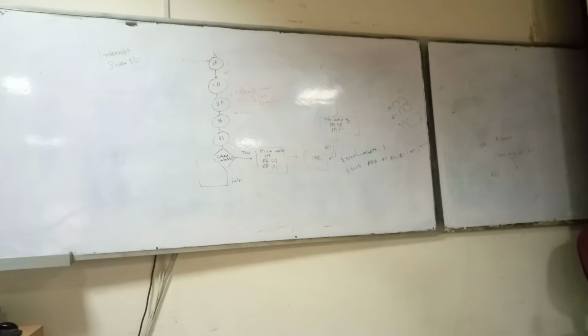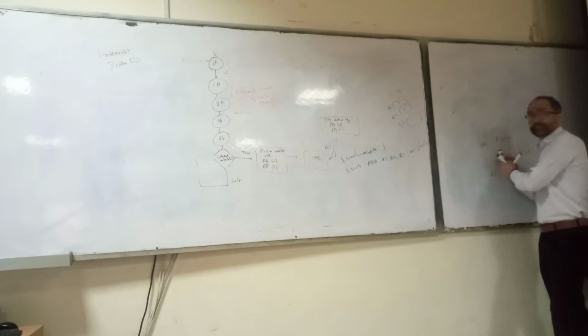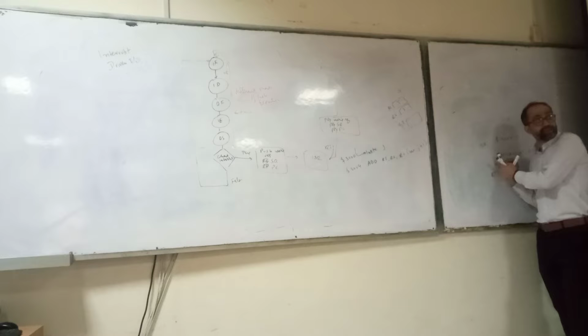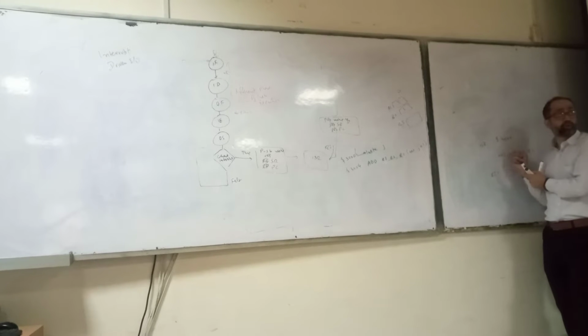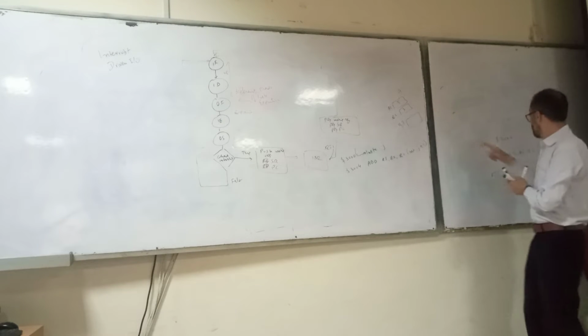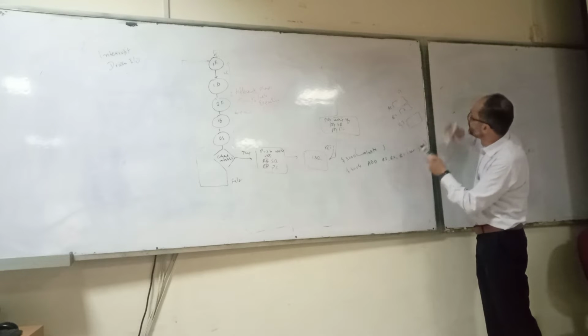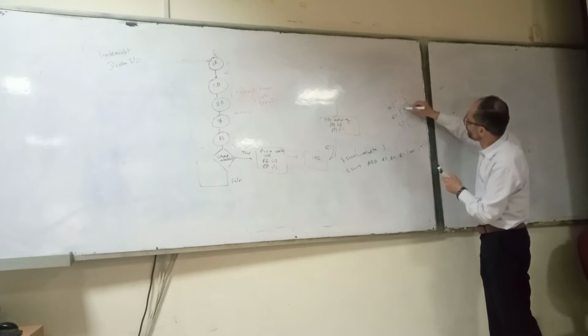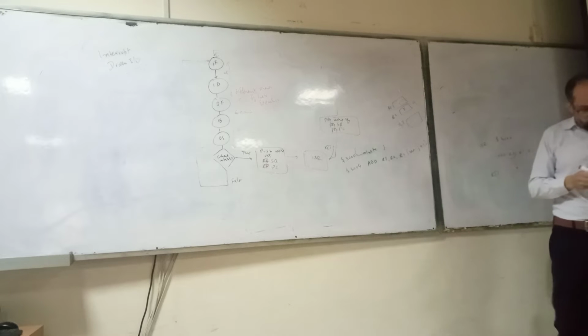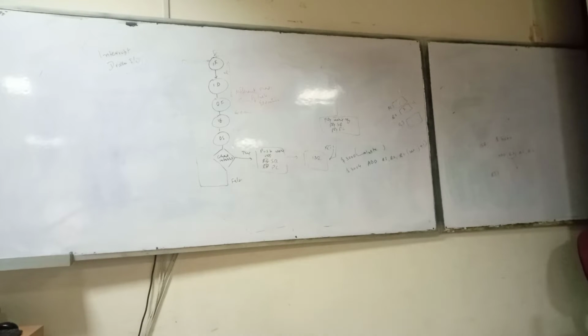The registers are actually temporary locations. They temporarily hold the data. But when it jumped to the ISR, you are changing the contents of the register R2. Maybe this register R2 was 5, and then it will be 9. So it will make the program inconsistent. The program will become inconsistent.